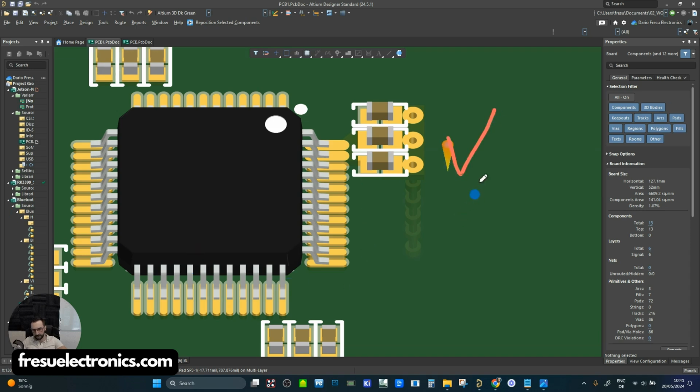So the voltage drop that we are allowed to have in the IC divided by the total transient current that we calculated before from the two main sources, so from the shoot-through current and from the transient load current. This simple formula will give us the target impedance of the board. And then we can use this target impedance of the board to calculate how many capacitors we need to have and what the total capacitance needs to be in order to guarantee this target impedance for low frequencies.